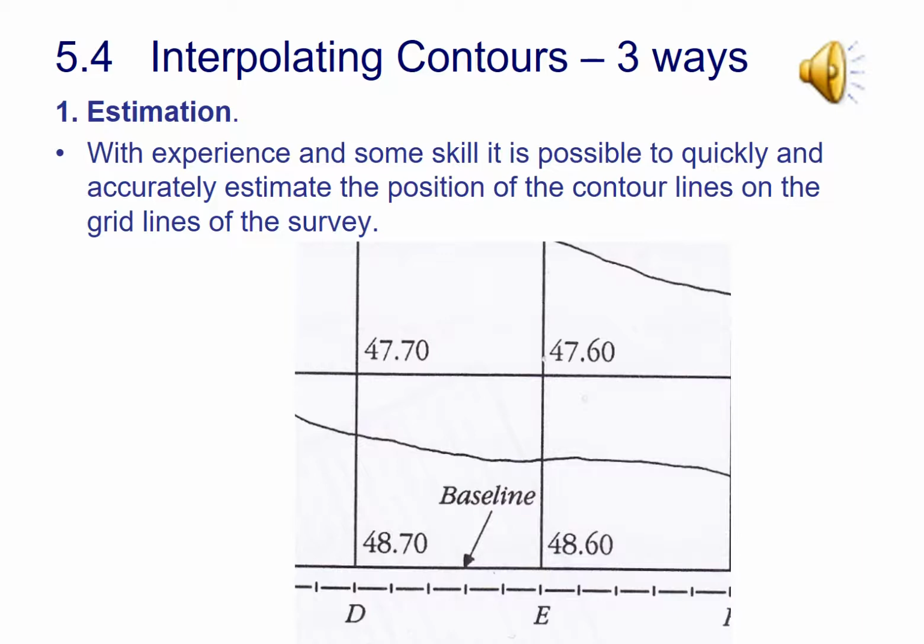could do that is with estimation, just to estimate it. And with some skill and experience you can do this. It's not particularly accurate, so I wouldn't recommend it, but it is a good way to check what you've drawn, because you will know instinctively whether it's correct or not. So if we have a look at the diagram here on the screen, I want you to look particularly at the levels between 47.60, so that's 47.60 meters above ordnance datum, and 48.60.